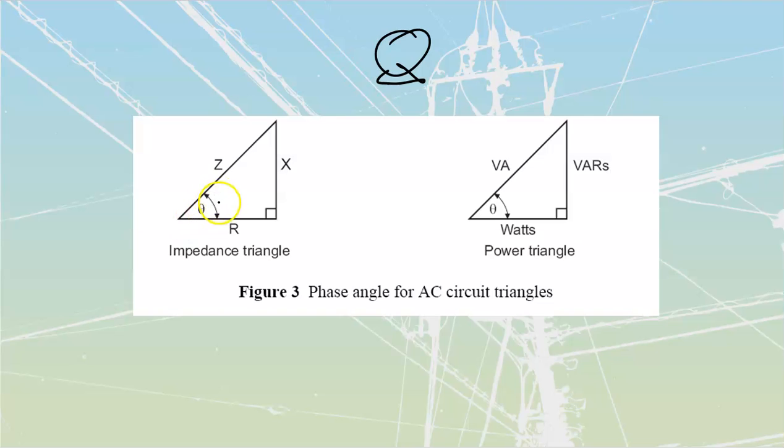If I'm given two values, the first example they give us is 60 degrees, as well as an impedance of 10 ohms, I should be able to solve this multiple different ways. There are at least two ways to solve this that should be immediately apparent. That would be for me to use either my sine, my opposite over my hypotenuse of 10, or my cosine, my adjacent over top of my hypotenuse for this one. Either one of those would work.